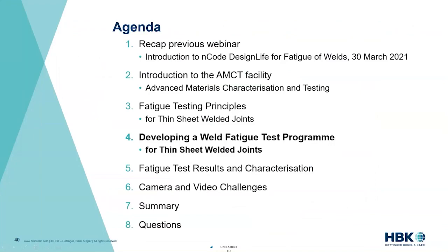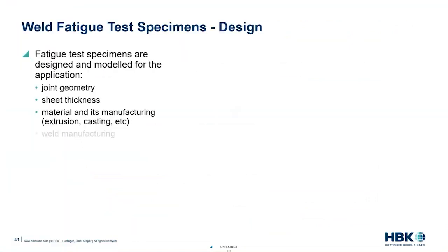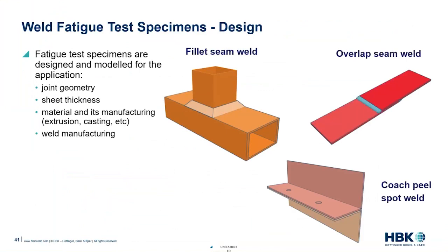So let's look a little bit at developing a weld fatigue test program. The test specimen is designed and modeled for the application. So what's the actual joint geometry? What's the sheet thickness? What's the material? How's it manufactured?